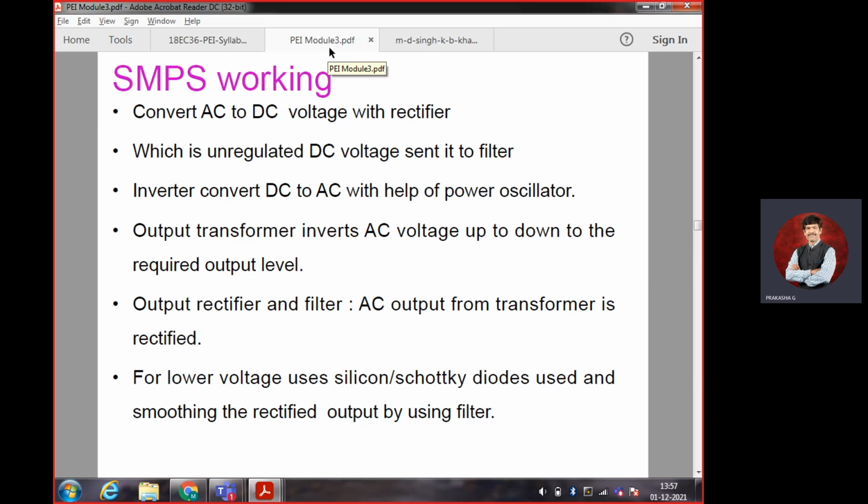Generally, as you have seen in the lab also, a small capacitor will be in the form of a silicon capacitor or ceramic capacitor. There are two types of capacitors: one is the electrolytic capacitor, and one is the ceramic capacitor. Both of them you have used in the lab. One is brown color and bubble-like, with two lines. That is a brown ceramic capacitor, and it is low in value. The electrolytic capacitor is blue color, where the gray band is on the side. That is the electrolytic capacitor, and it has high capacitance.